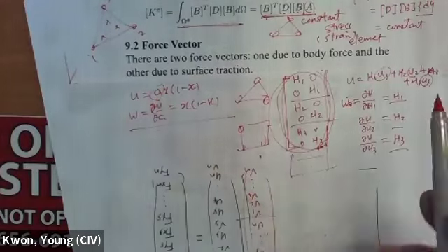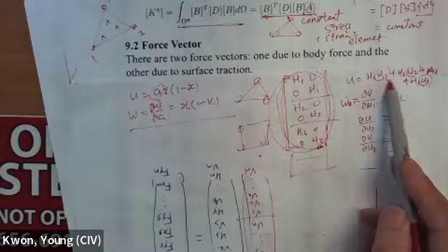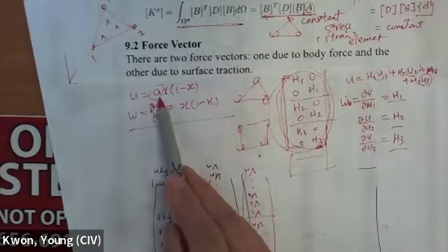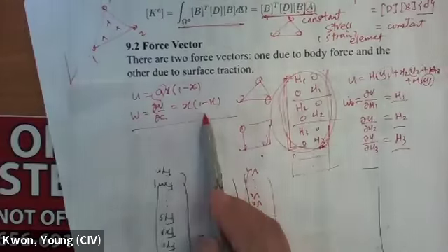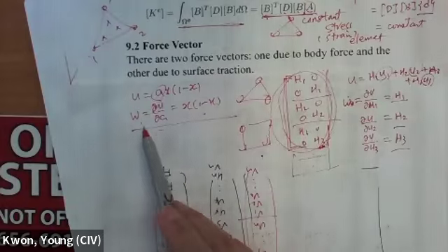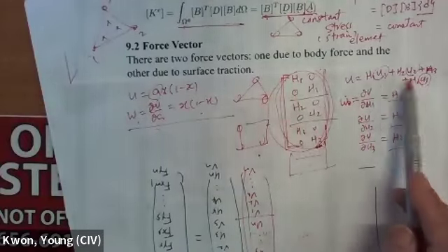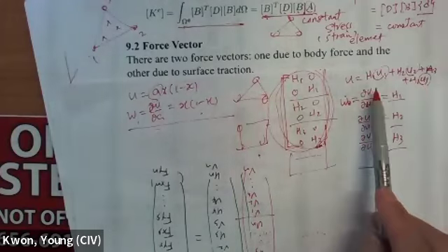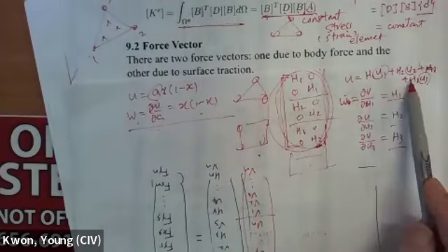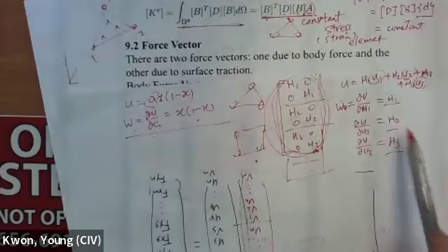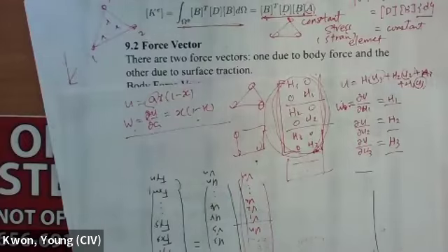This A is equivalent to the nodal displacements U1, U2, U3 here. So in this case, you have one variable, so you take just one derivative and one test function. But here, you got U1, U2, U3, three different variables. So I need to take a derivative with respect to U1, U2, U3. That's what you get, H1, H2, H3. So you got these three shape functions, exactly the same as what you use for your solution U.